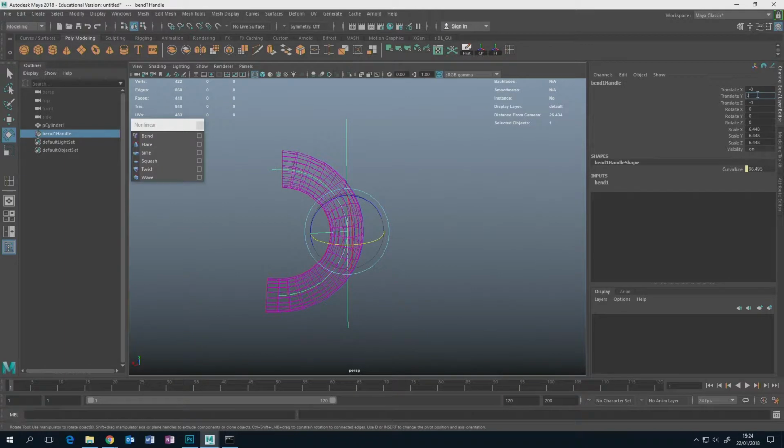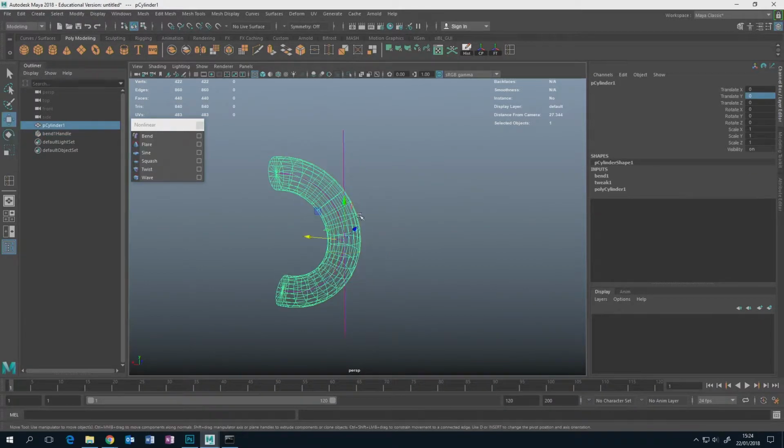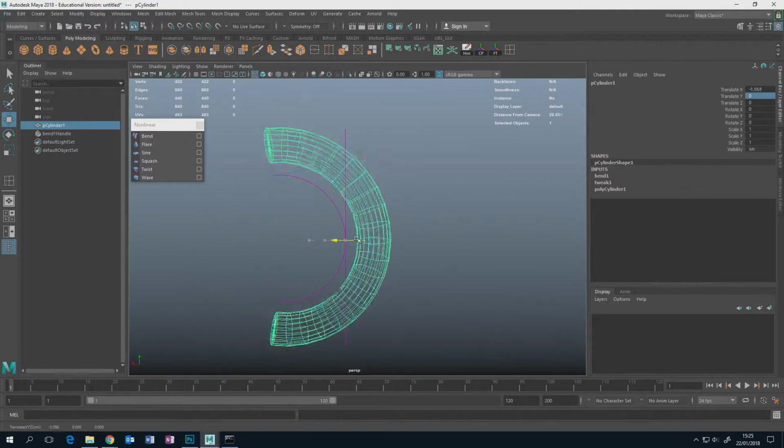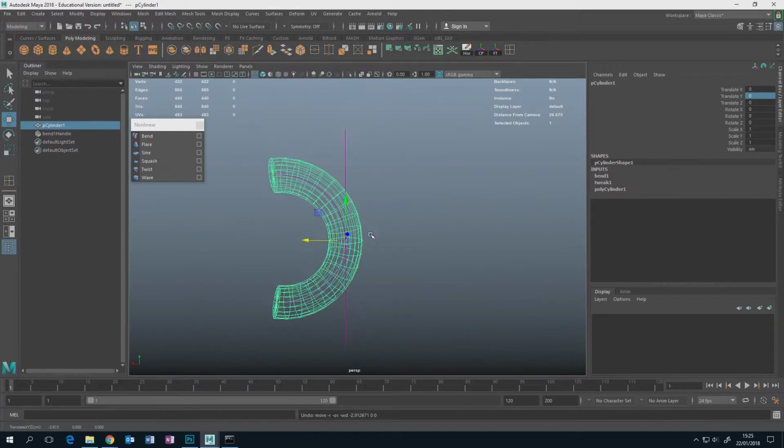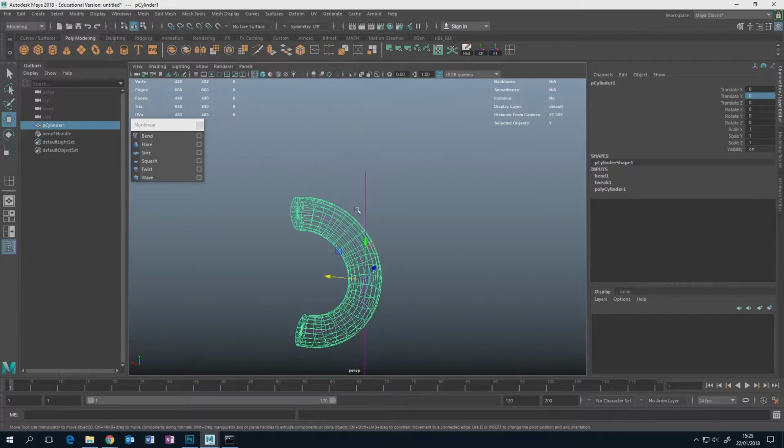But anyway, you want to use this mesh tool here. Insert Edge Loop is a bit fancier than this one, because with this one, if I open up the menu, I'm going to reset the tool. I've got the option of setting multiple edge loops. Maybe it's a common thing that I always want to take two edges and evenly split them up into 3 or 4. If I go into multiple edge loops and say 3, now when I click an edge, it just evenly splits them up. I'm just going to turn grid off. I might need to do that lots and lots and lots.